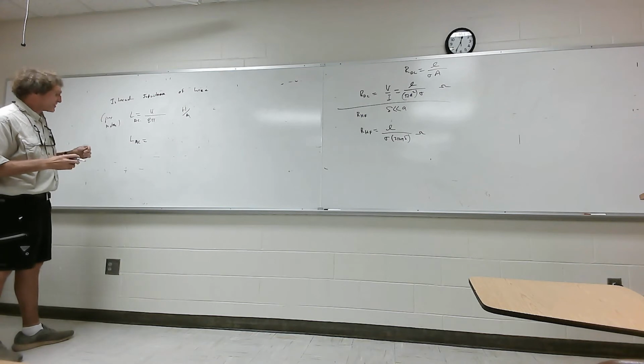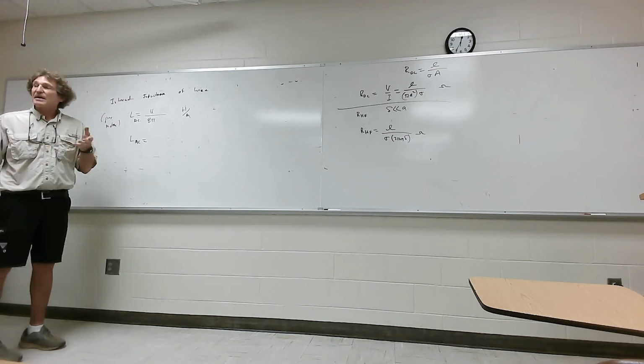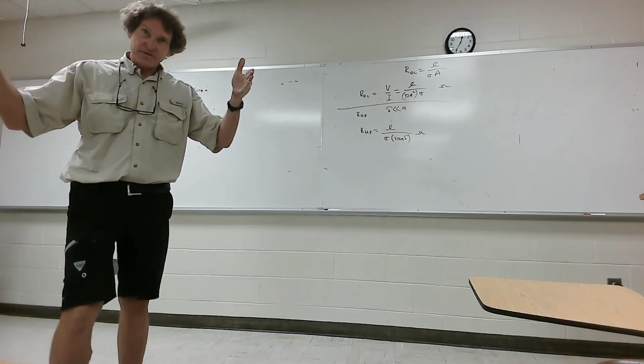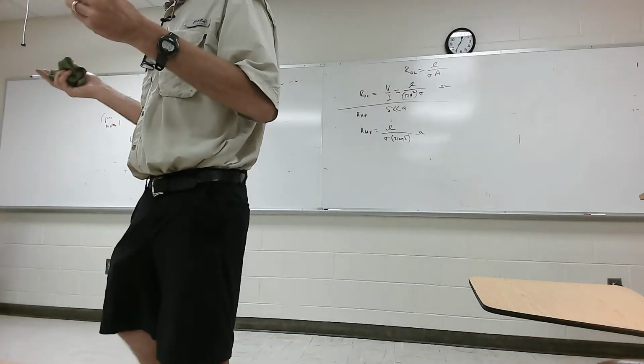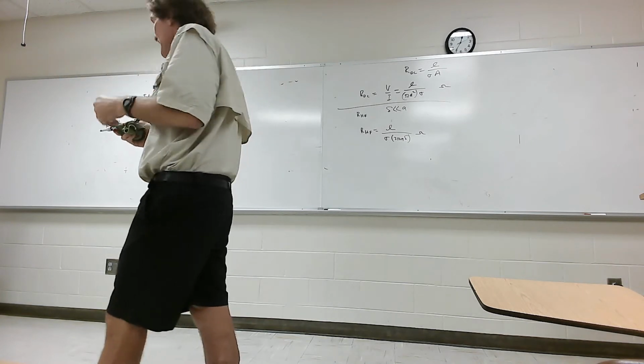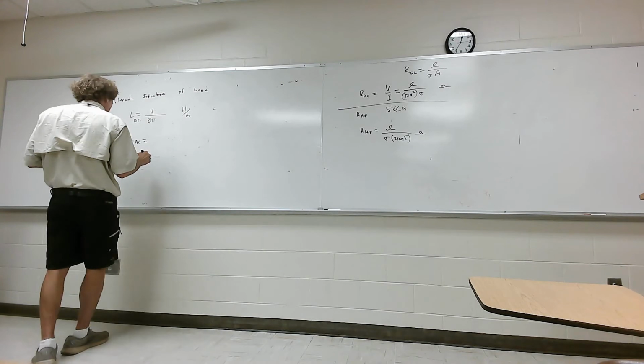Okay. The AC internal inductance, and I'm not going to prove this, frankly, because right now I don't think I'm going to have time to. But what you have to do is say all the current is limited to the skin depth. Then you have to calculate the H field. From the H field, you get 1/2 mu H squared. Then you have to integrate that, set it equal to 1/2 L i squared. At the end of the day, it's the same thing.